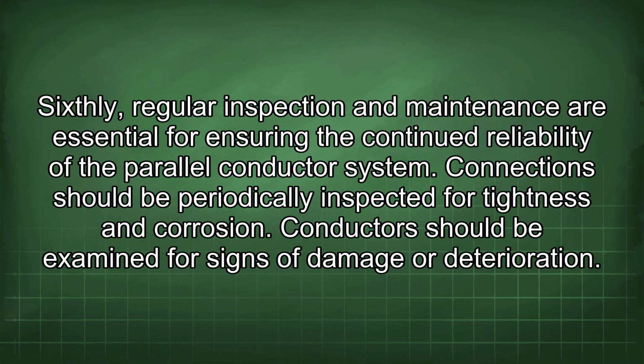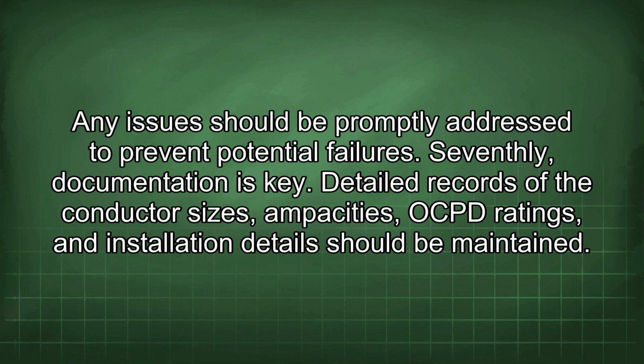Sixthly, regular inspection and maintenance are essential for ensuring the continued reliability of the parallel conductor system. Connections should be periodically inspected for tightness and corrosion. Conductors should be examined for signs of damage or deterioration. Any issue should be promptly addressed to prevent potential failures.